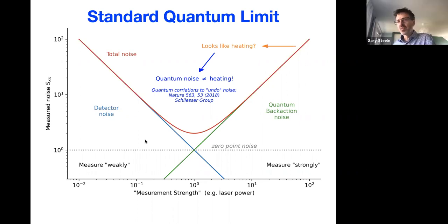Oh, for sure. Yeah, no, definitely. I mean, that's super interesting, actually. So what's different about what we do, the commercial SQUIDs are all based on DC wiring. You do RF. And there we do RF, and there you have a big advantage because you can use the low noise amplifiers, you can use parametric amplification, and really get down to the quantum noise level, which is very hard at the DC SQUIDs.